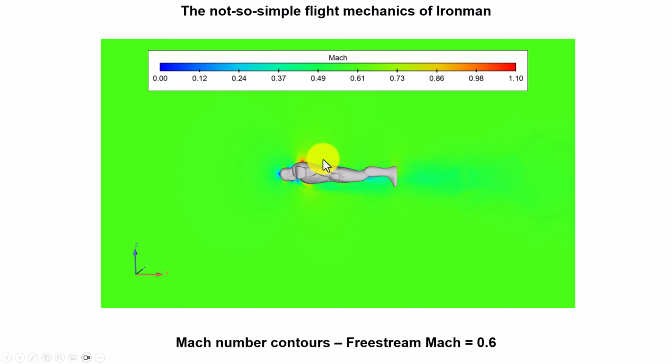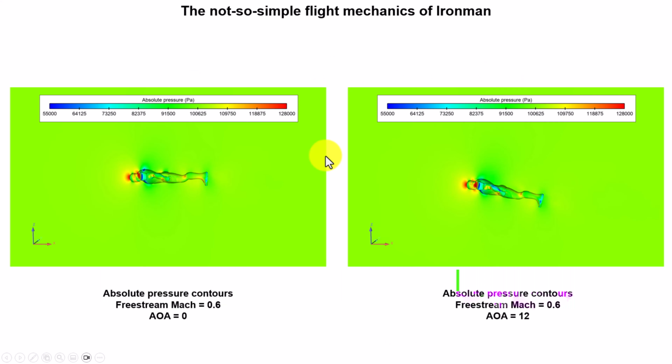So I increase to 0.75, where you're going to have shock waves in many zones, so things will get really bad, and the performance, the L/D, will be even worse, and who knows what other problems. Thermal heating for sure is going to cause some problems. Well, we know that it is a crazy alloy that we are using there.